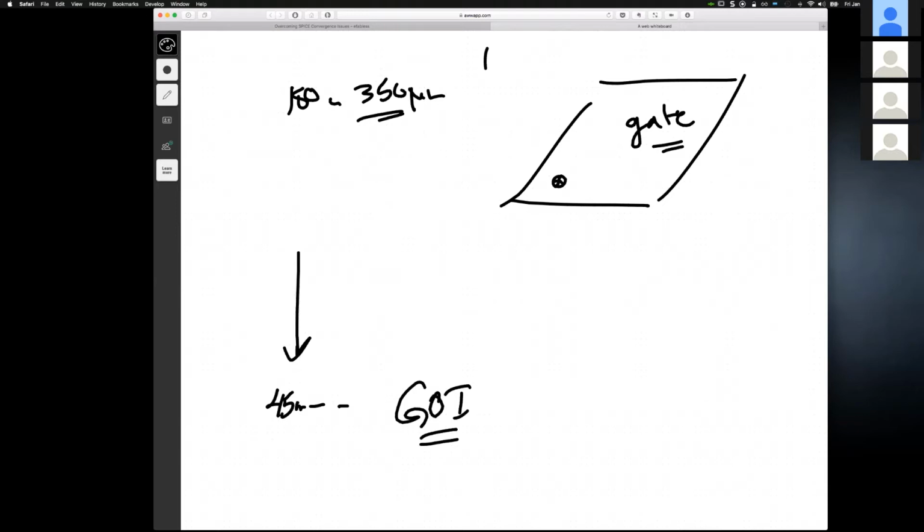But Mohammed, can I interject? This is definitely true for 45 nanometer, and I know that there are problems as soon as you get below 180. But I'm not aware of any specific maximum device size specified by XFAB for the 350 process. Yeah, so I agree with you, and that's why I said the answer is yes. There are practical limits, but no specific limit. In general, thank you, Tim.